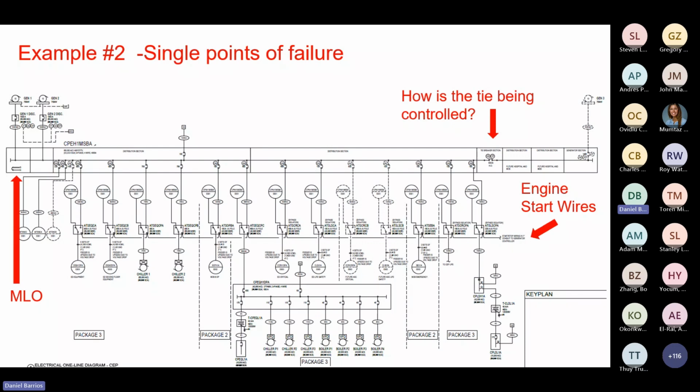In the case of when you're also doing, the reference will be at the end, you have to monitor each of those start circuits so that you know that if any one of those are broken open, according to the NEC, it is going to start the generator to notify you that you've lost that start signal. In this case, if you've broken that daisy chain, you may affect many more switches downstream or such.